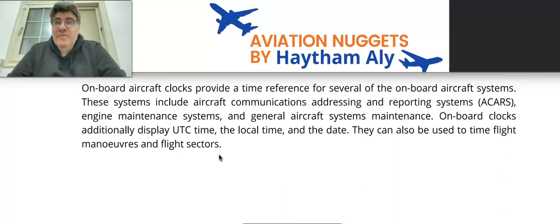Some aircraft components have what is called a duty cycle. In order to operate such a component, you must make sure that you are not exceeding the timing limitation of operation of this component. Otherwise, it may fail and it may lead us to another big problem. So for all the components that have a duty cycle, like the starter of the engine, you need to operate the component with reference to a stopwatch or chronometer.